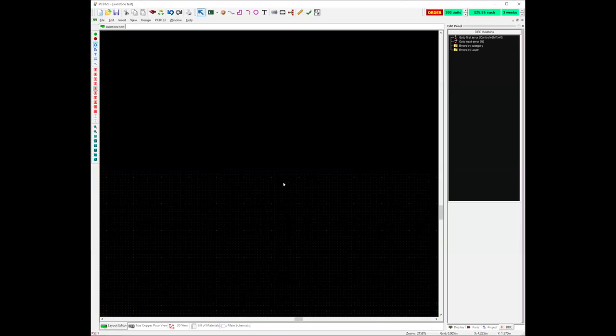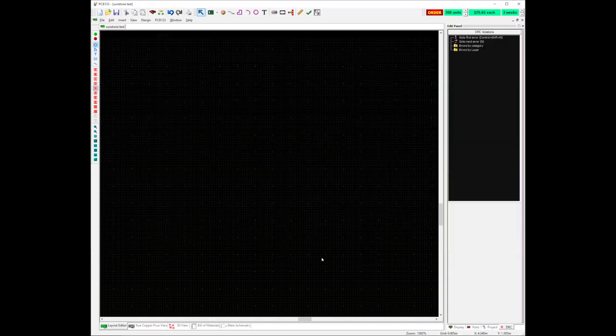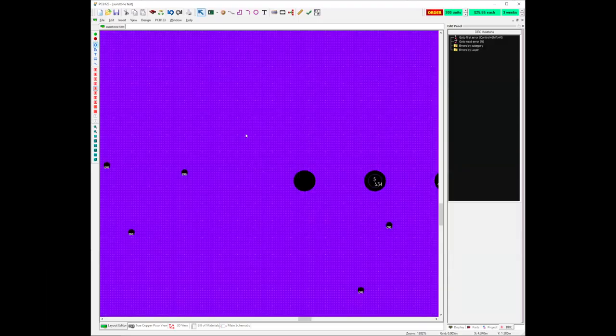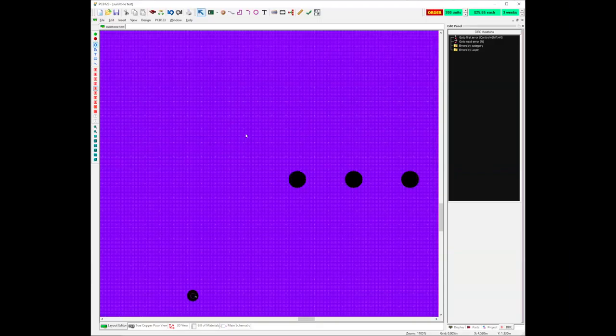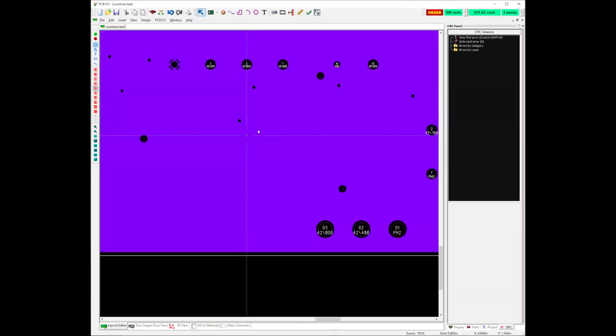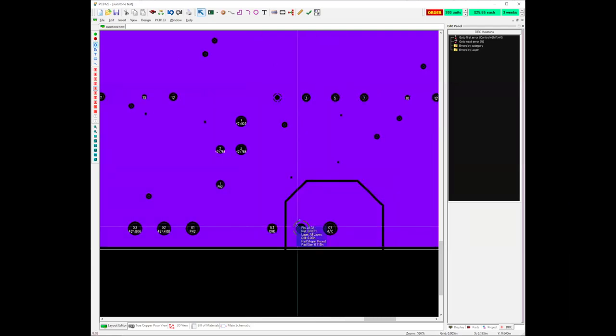So adding more than one net to a power plane layer and then trusting your knowledge of the circuit and where all of the parts are and visual scans of what's going on with your board to make sure that you didn't short your plane layers together adds a huge amount of responsibility to you as the designer that you didn't short something together.